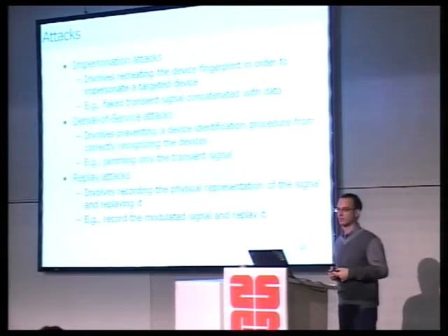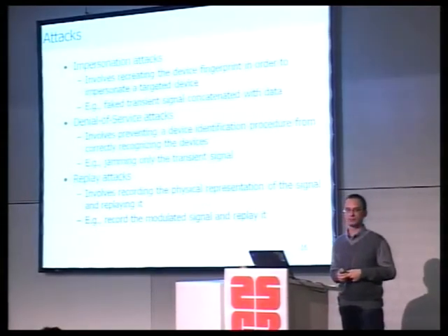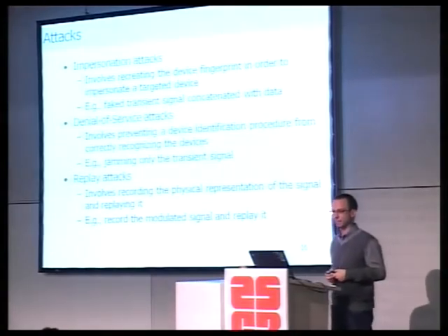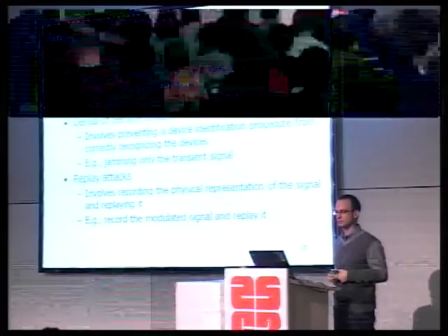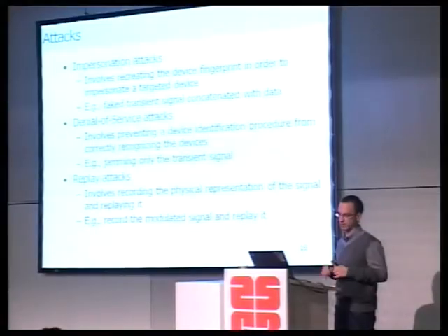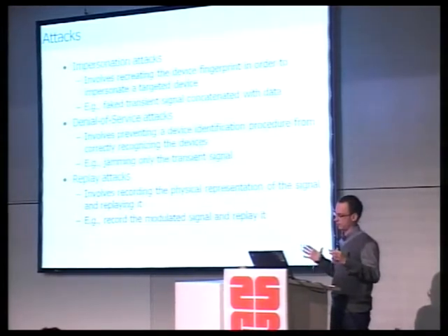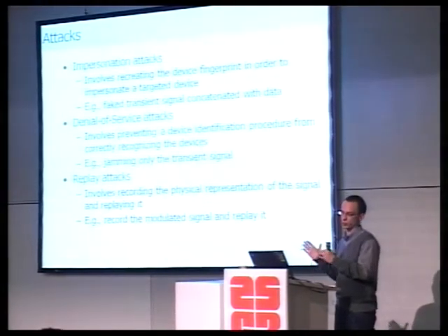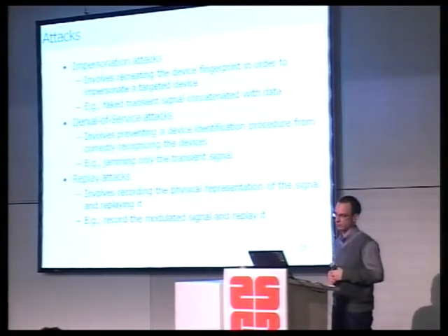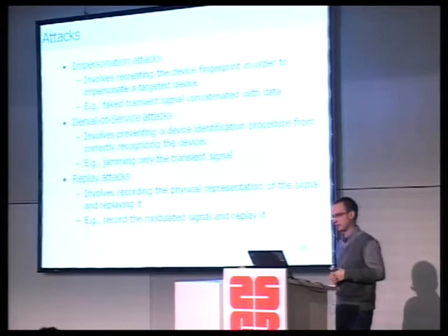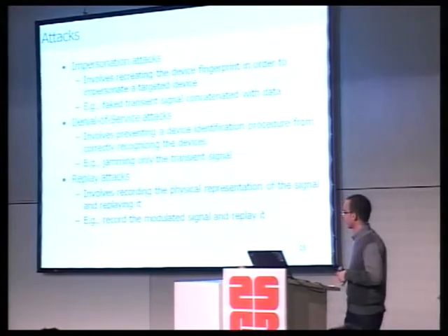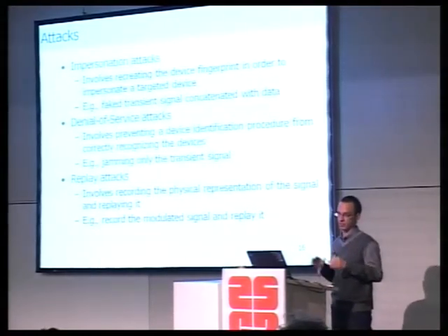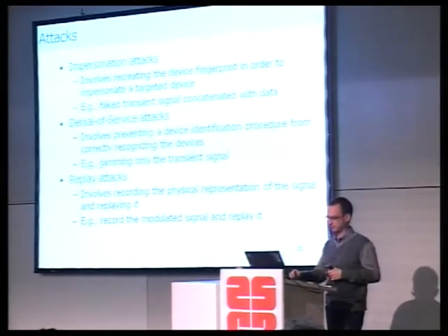Yeah, questions on the attacks? Yeah? In replaying the signal, wouldn't you still have to match the antenna polarization? Exactly, yeah. We also have to match the antenna polarization and use very expensive signal generators that are able to completely reproduce the signal originally at 2.4 gigahertz. This equipment is usually more than 150,000 euros, so until now, little success for us. But if it's possible to replay this kind of signal, we'll break the system.